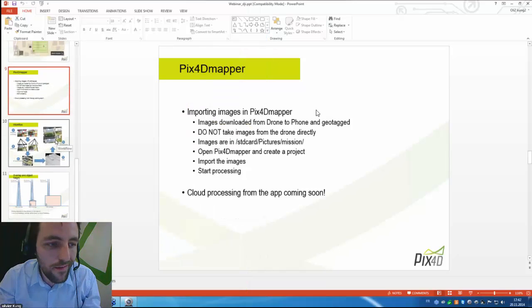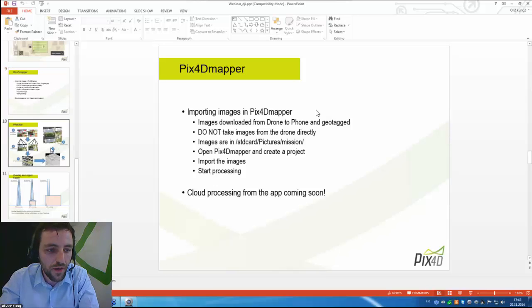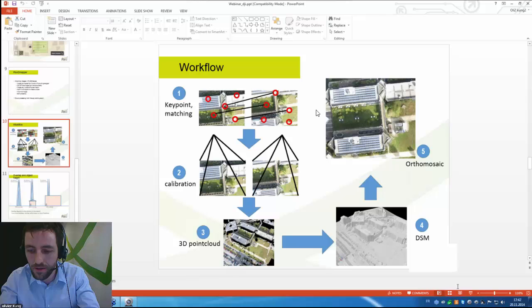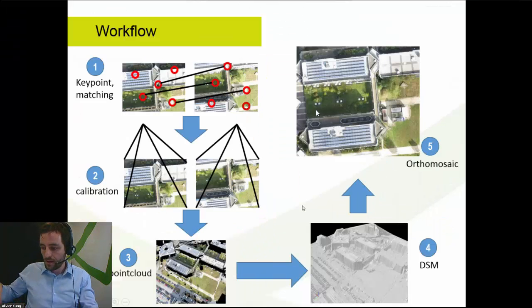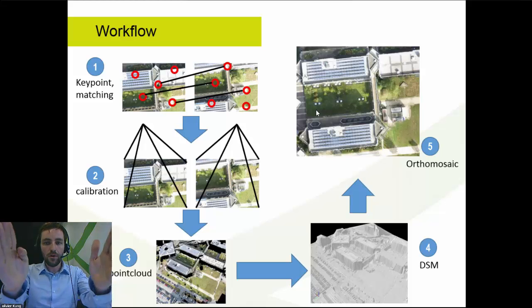Okay, so a little introduction on photogrammetry to get a better understanding of what happened between taking the images and getting a 3D model. So the whole concept is based on image matching. It's based on comparing the different images, and by doing enough computation, you are able to find back the 3D dimension that you lost when you took a picture. When you take a picture, you are losing information of the distance to the object, and as well, because you have perspective, the objects are changing shape.